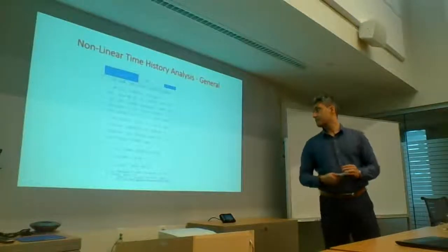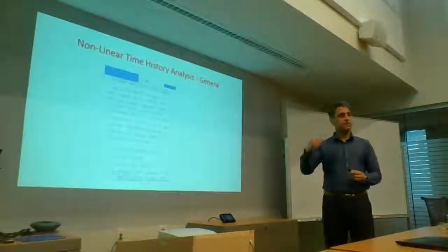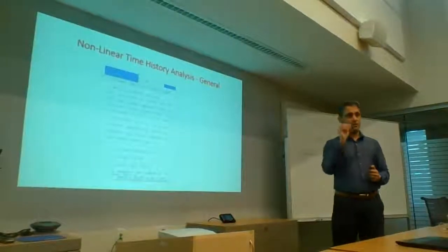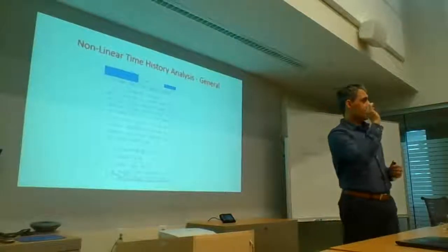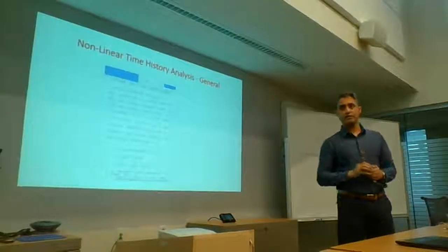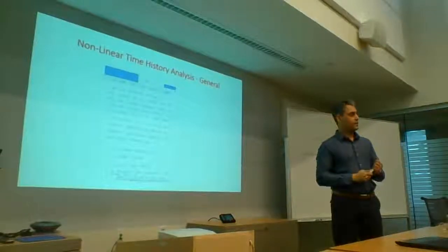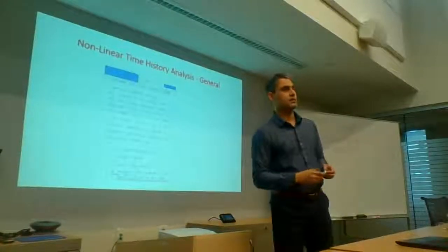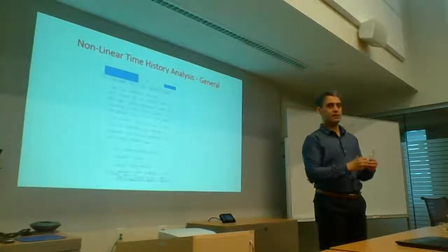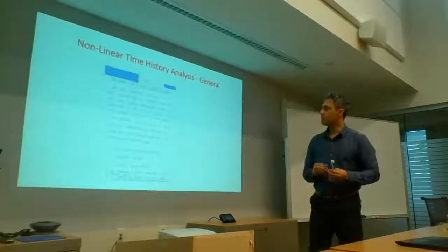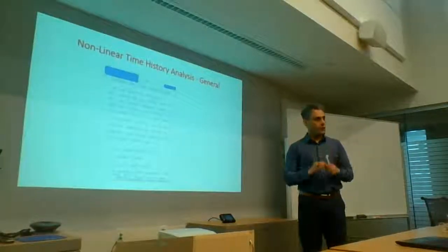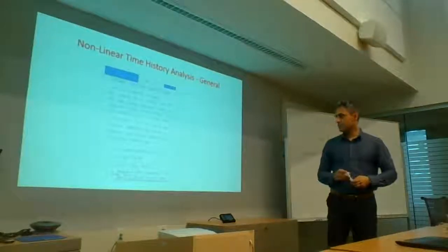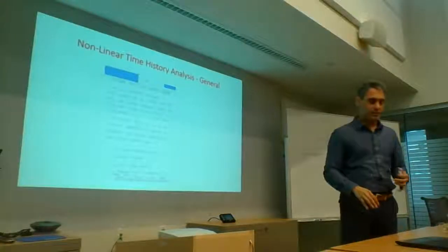Some of the procedures that you'll find are time stepping procedures. The earthquake accelerations are going to be digitized, their values given at very small intervals, perhaps a thousandth of a second or a 500th of a second, and you step through the analysis. You've got your acceleration coming into your system at very, very small intervals, and you solve for each time step, and then you march forward in time. Some of the methods are the central difference method, Newmark's method, and Wilson's theta method.